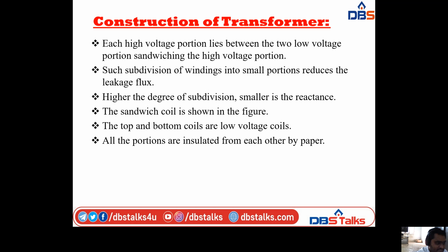I will discuss the sandwich coil. Each high voltage portion lies between two low voltage portions, so the high voltage portion is sandwiched. Such subdivision of windings into small portions reduces the leakage flux. This is one way to reduce the leakage flux.